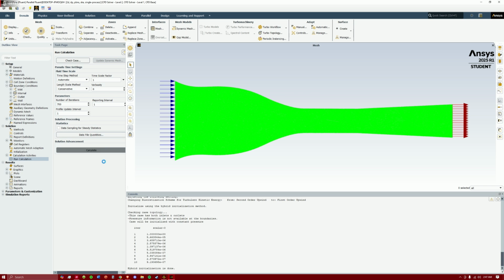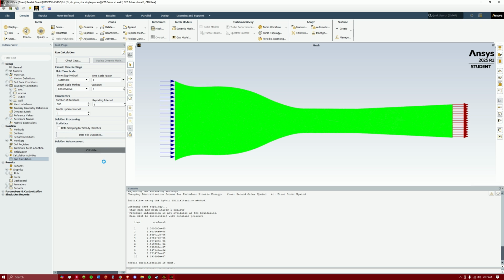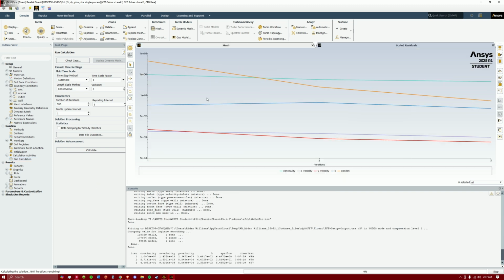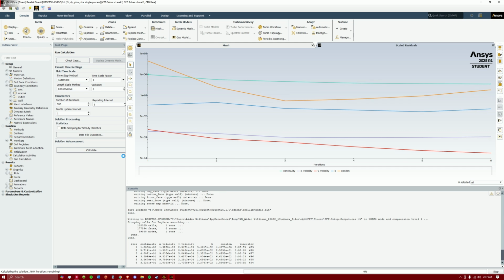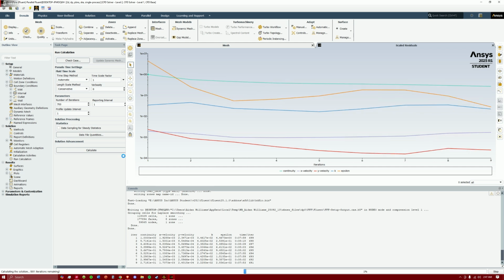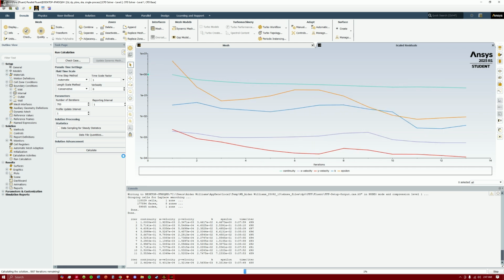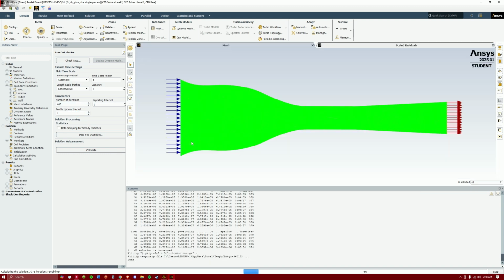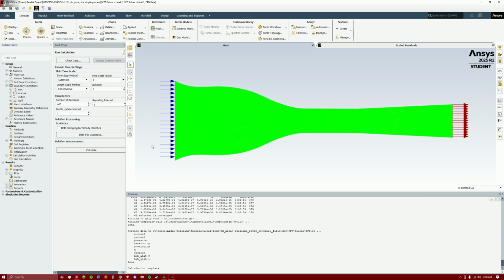I go higher for more accurate, lower for faster, but for the sake of time, I'm just going to do 700. It should solve it out before that. Yeah, okay, there you go. If you're running it on base settings and it goes over like 300, something's probably wrong.